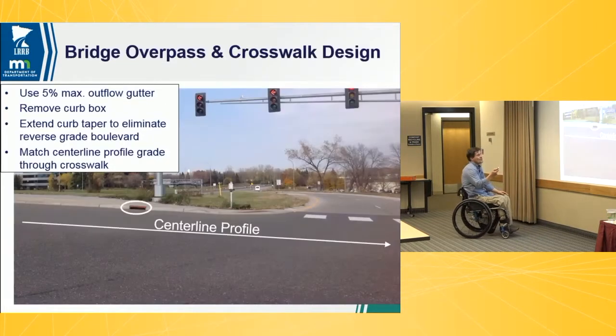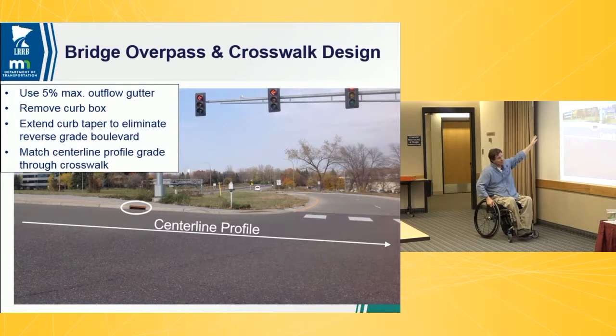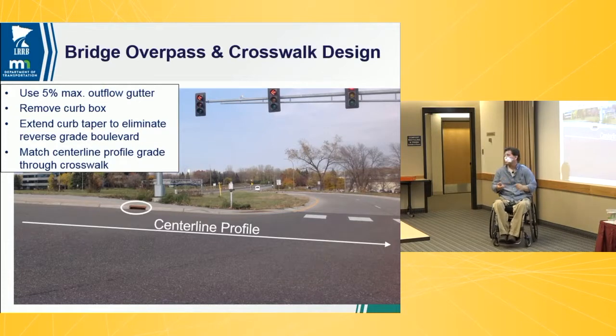So also with crosswalks, this is our interesting situation. This is a grade separated interchange, and we've got a freeway ramp over here. But this could be any downhill that we have, again with a side street, so it works in multiple locations. Quite often these types of things have a good slope to them, if it's grade separated, you know, 3, 4, 5, 6% sometimes, up and over. And again, all you have to do with ADA is match that profile, so it should be easy, right?